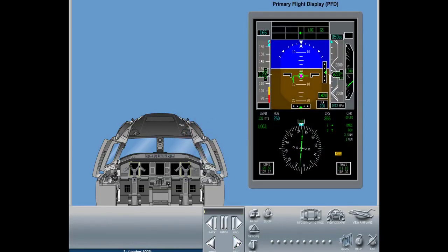The primary flight display, PFD, is the flight crew's primary instrument. It provides display of aviation and navigation information as well as backup radio tuning. The PFD is divided into sections, each one presenting one group of information such as information regarding airspeed, altitude and vertical speed, attitude, heading, flight modes, and tuning COMMS and NAV.